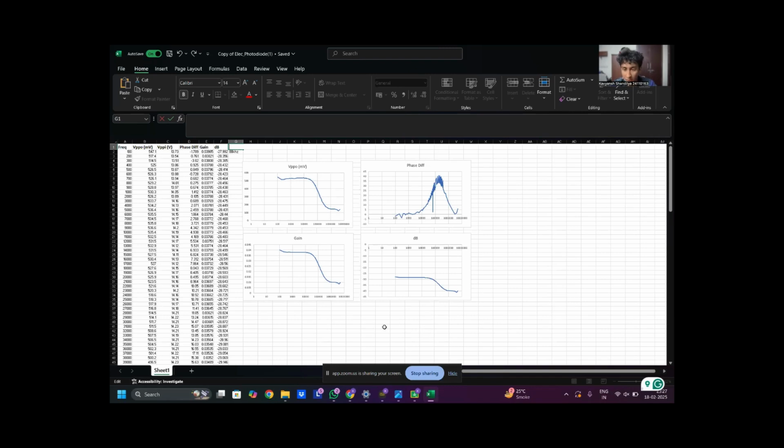To summarize, we observed resonance in the piezoelectric sensor and calculated its quality factor, helping us understand its sensitivity and frequency response. Meanwhile, for the photodiode, we determined its 3 dB cutoff frequency, which is essential in evaluating its bandwidth.